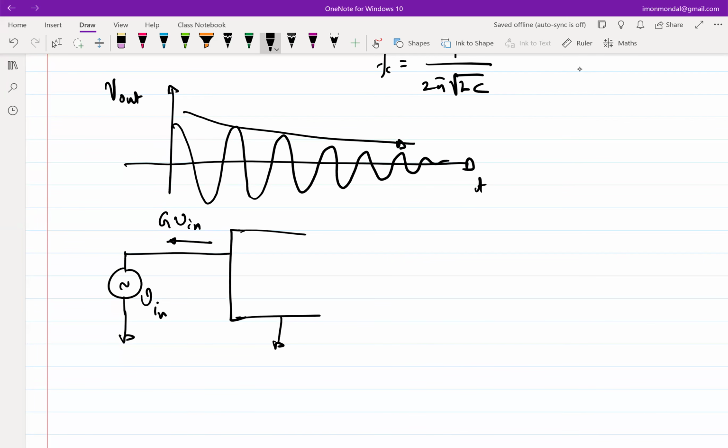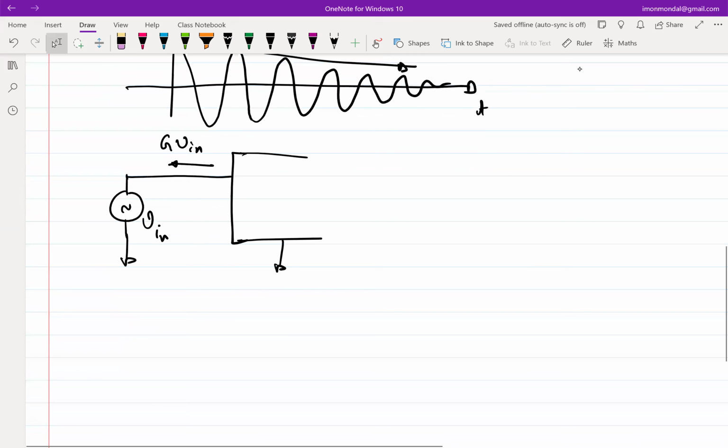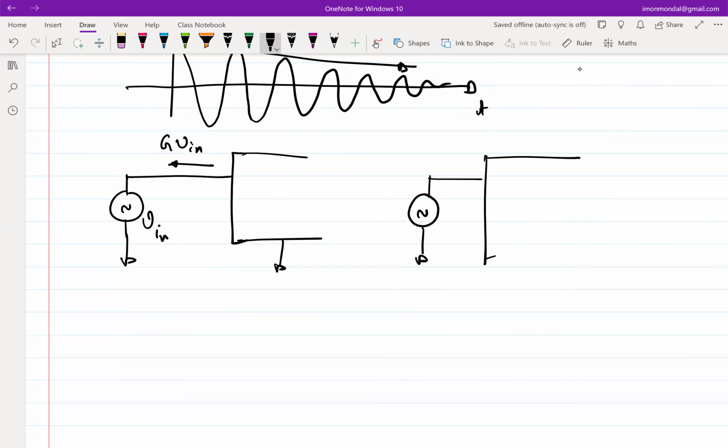So that should be pretty intuitive to understand, what needs to happen in order to get a negative impedance. Okay, so let's say I ask you, using a transistor, you have to generate the opposite. So the one that you are familiar with. Let's say I ask you to generate something so that if this is V in, current is in this direction proportional to V in. Obviously, you can put a resistor which gets a current which is proportional to this. But let's say I do not want to put a resistor, because ultimately with a resistor I cannot go to the circuit on the left. So some sort of active device. What is the thought process? How will you go about doing that?